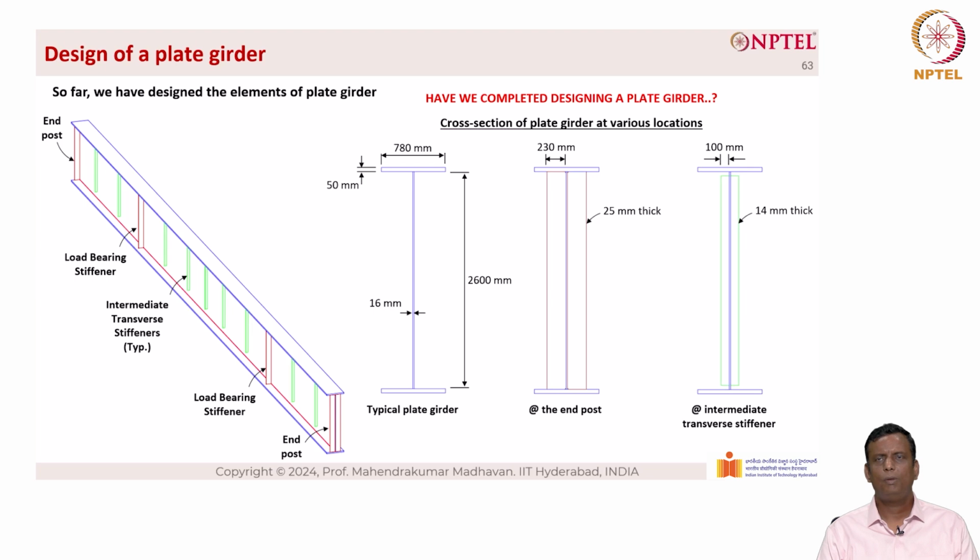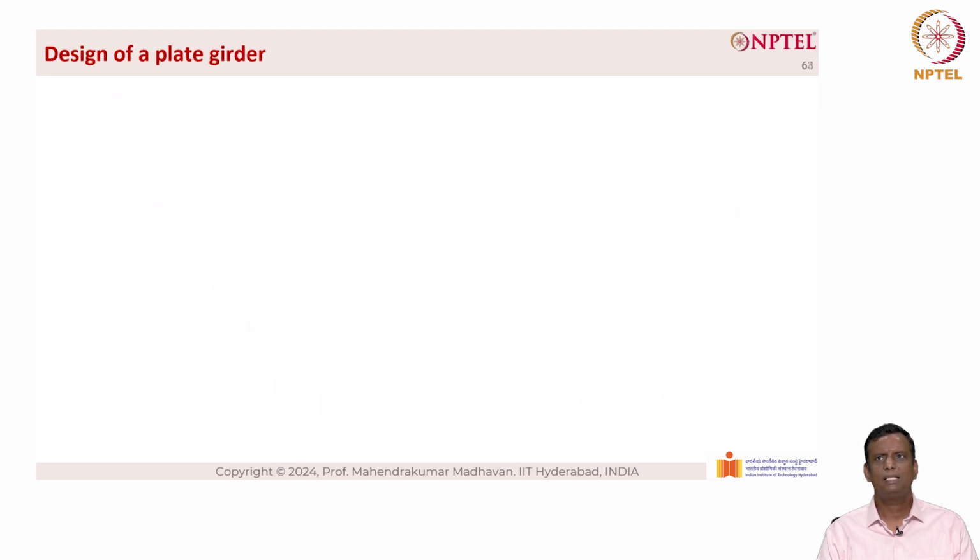Now, we may think that we have completed the designing of the plate girder, but what do you think? I think there are many things that we need to take into consideration. This is just preliminary sizing of the girders, and we have not completed the design unless we have completed the connections as well. Connections is a major thing that we have ignored in the design of the plate girders. So the answer is no.